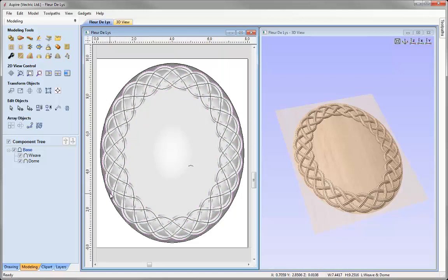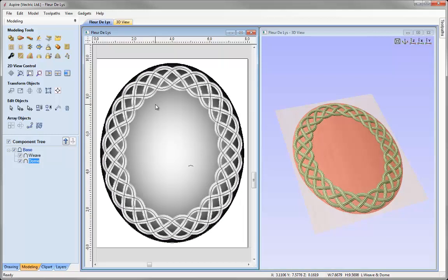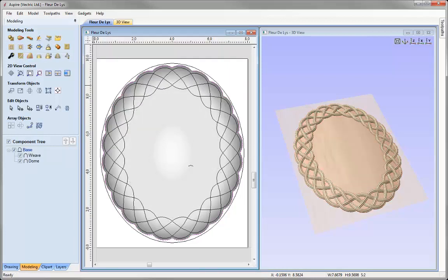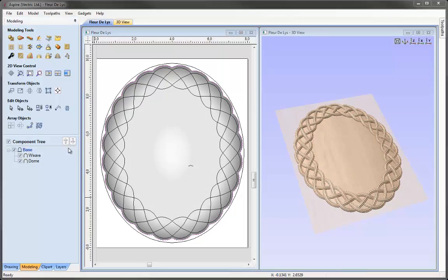with this outer vector. So now I can take that dome shape, I could hold down Shift and select that outer vector, and we're going to come over and use this option here to clear area of selected component outside selected vectors, and that's just going to remove everything outside of that vector. So now I'm happy with the shape that we've got there.